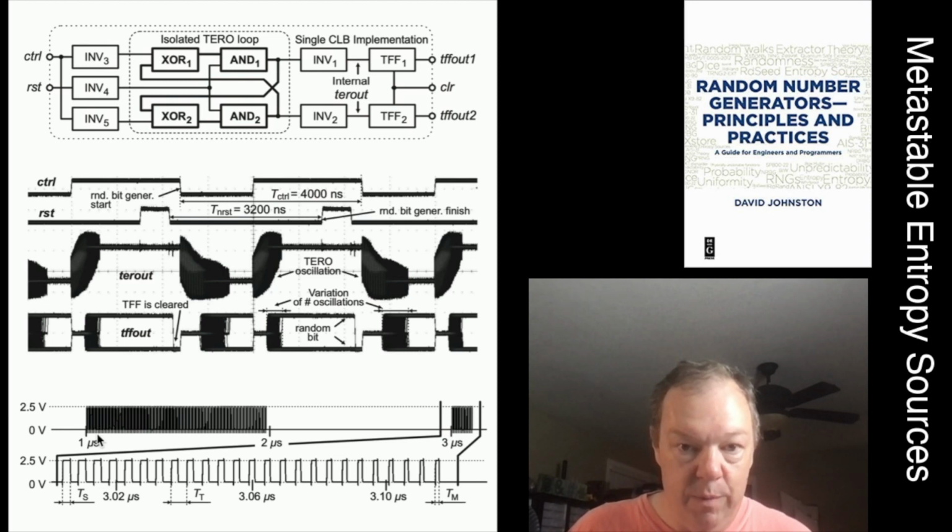Now what's happening with those pulses, it starts off with these pulses going around and around the circuit, and you see they're getting thinner and thinner and thinner, until they're sufficiently thin that they disappear. Because there's nothing keeping these pulses stable, some noise is causing those pulses to lose timing and become thinner. So that's a quite neat design because it's built with multiple digital components, not with any analog components. So you can build that in an FPGA.